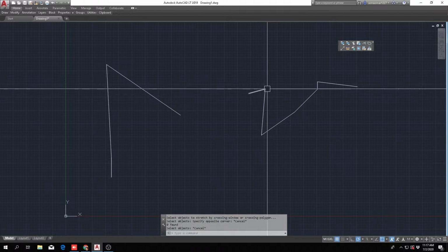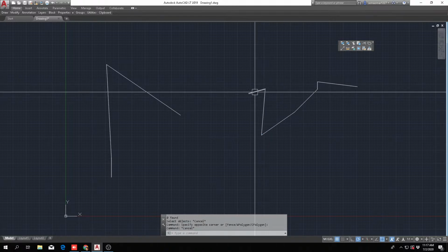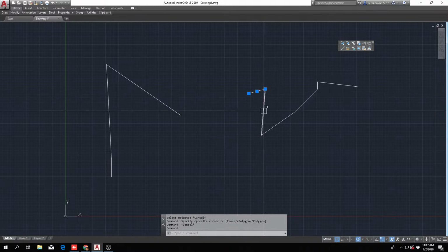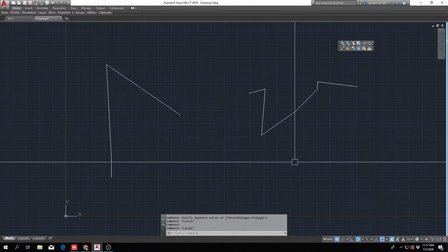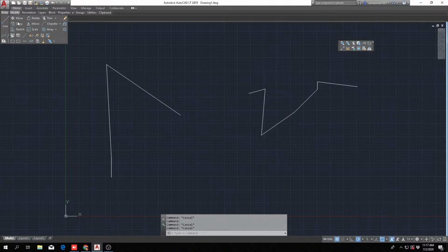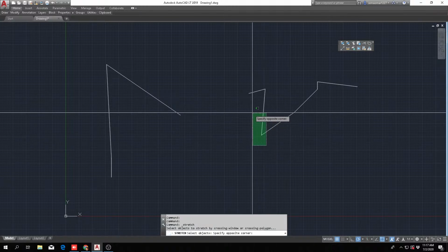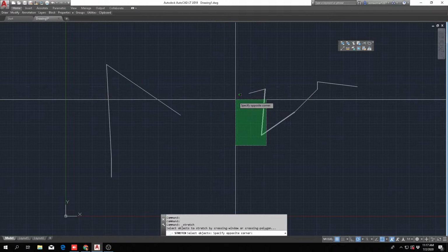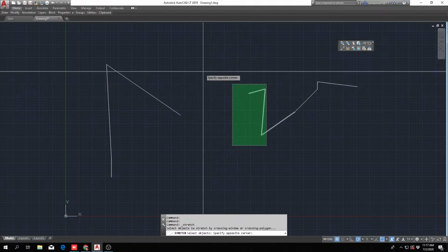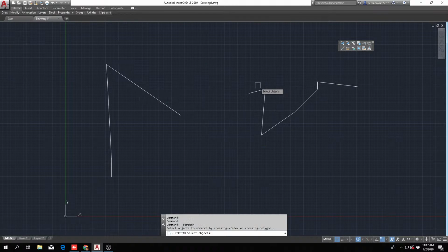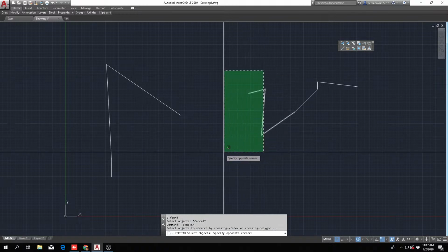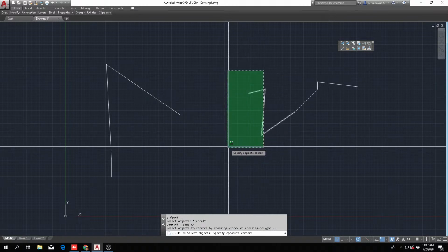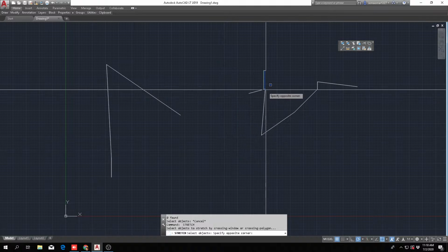Now if you wanna keep this point right where it is, and you just wanna stretch it from here on, and this from here on, and this from here on, then make sure your stretch window is only touching that area that you want to stretch. Once again, here is not touching that. So this one's going to be a little bit complicated. I guess I need to start from over here. There you go. Then you see how I didn't get that vertex right here, or that point.